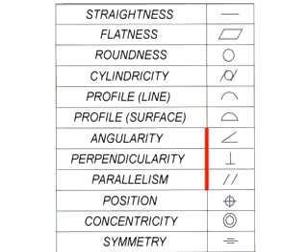It's got to be parallel to something else. And that generally implies that that something else already has a geometric tolerance applied to it. Let's say flatness or straightness. If you want something to be angularly correct to something else, well, that something else had better be flat before you figure if the second surface is at its proper angle to it.